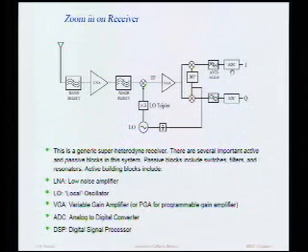So the ADC here is an analog to digital converter. These blocks here are filters, and you can see that filtering is a big part of what a receiver does. The first block, though, before we can actually mix the signal, is a low noise amplifier. The job of a low noise amplifier is obviously to amplify the signal, but to do it in such a manner as to add as little noise to the signal as possible. This is important because, as we discussed, in a receiver the signals can be very small. We also need an oscillator, a reference frequency that lets us do the frequency translation.